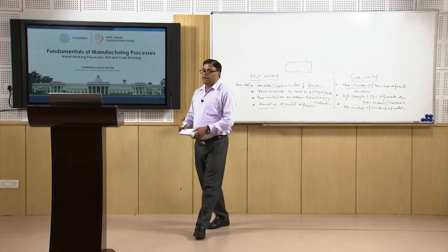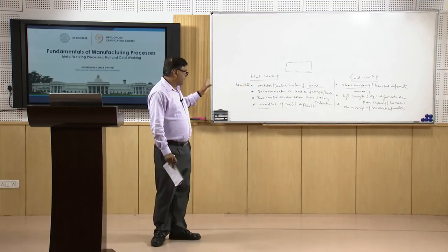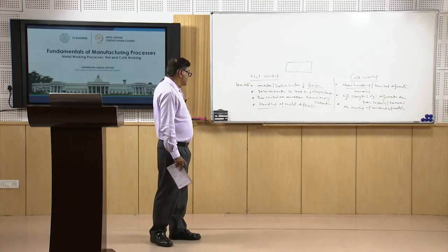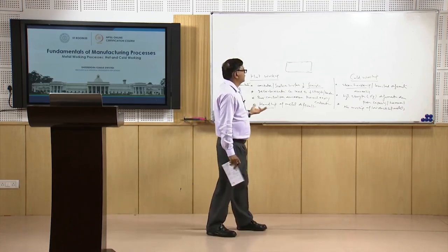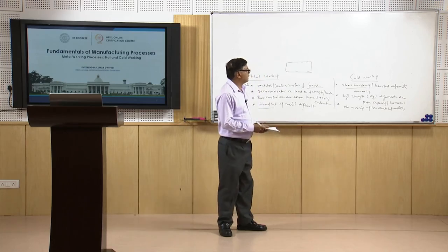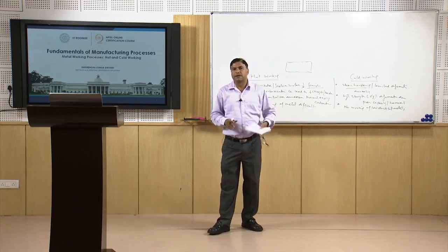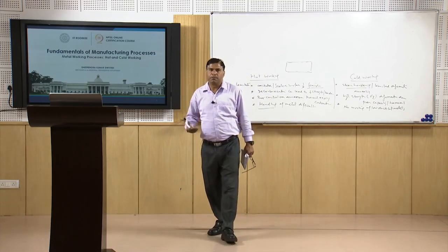So, here what we have seen is that hot working is easier to carry out, but it leads to the poor surface finish and poor control over the dimensions, while the cold working makes the deformation difficult. It requires more forces and more power consumption.